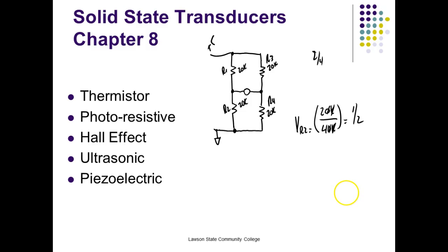The individual voltage drops in a series circuit have to add up to the applied voltage. Two resistors, if they're the same size, drop the same voltage. So this guy right here's got to be dropping 2.5, and this guy right here's got to be dropping 2.5, right? So right now I'd have plus 2.5 volts right there, and plus 2.5 volts right there.